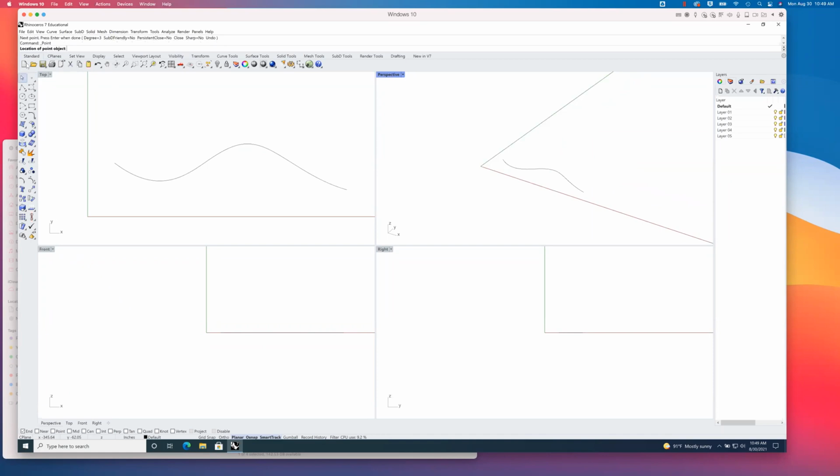But if I want to make a point, I can of course click and snap someplace in this Cartesian coordinate space, make a point. But what I always do, again, you've been doing parametric design, you just didn't realize it. Every time you hit a tool in Rhino or any of your other software, it asks you for the ingredients it needs and some of the parameters that it needs. So in this case, the location of the point object, I can type in 0, 0, 0. I can give it an X, a Y, and a Z coordinate, and it's going to give me a point right here at the 0, 0, 0 point.